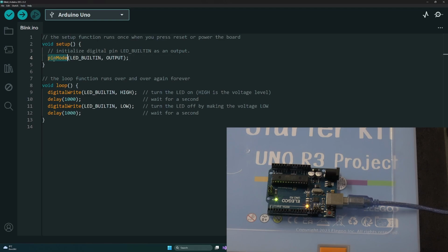So with Arduino, you're just going to tell the Arduino by calling this pinMode function with LED_BUILTIN and OUTPUT, well, this is the output pin, and then I can digitalWrite to it, I can delay, and I can make it blink. Now, all of these functions, of course, are coming from the Arduino software stack. So if you are doing plain AVR code, you are not going to have these functions. For sure not.